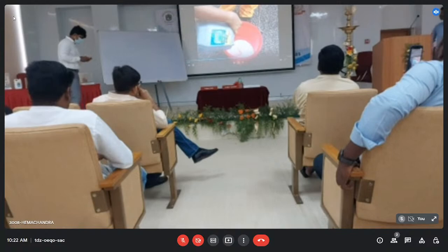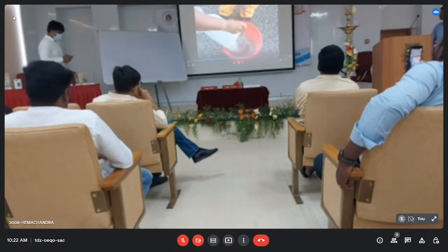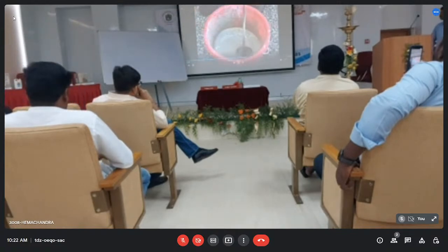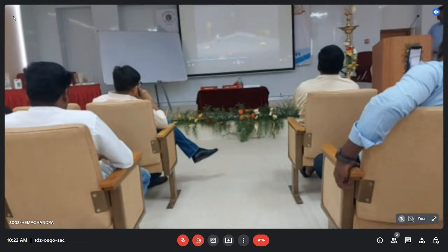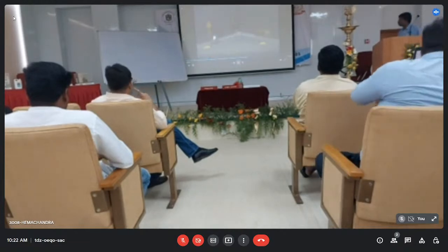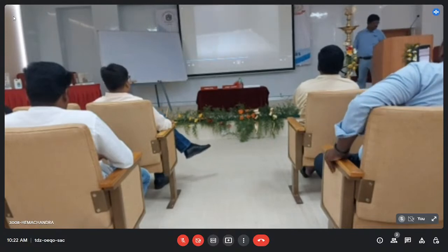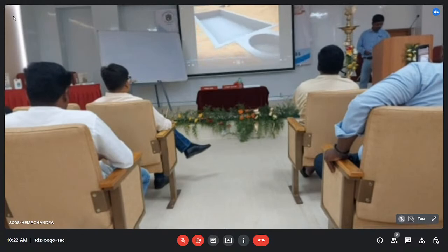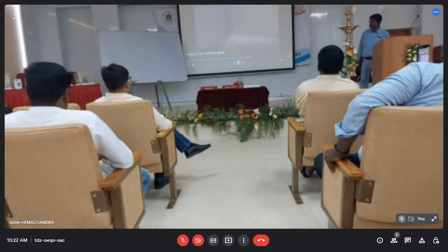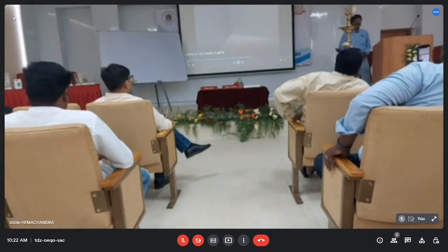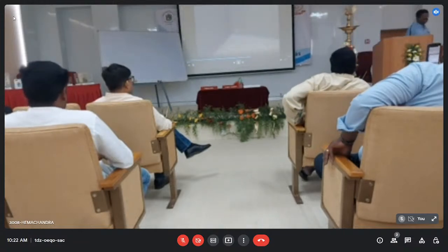Now, prepare a third batch of Dr. Fixit Fast Flex as before. Apply a third coat of Fast Flex. The direction of this coat must be 90 degrees to the direction of the second coat. While wet, sprinkle coarse sand on the coating. Because the surface is a vertical surface, you have to sprinkle the sand. It will act as a mechanical bond.